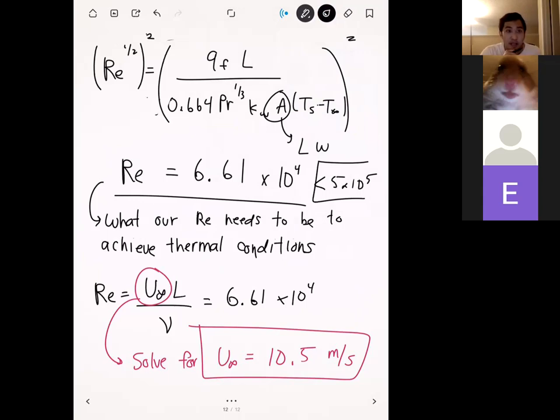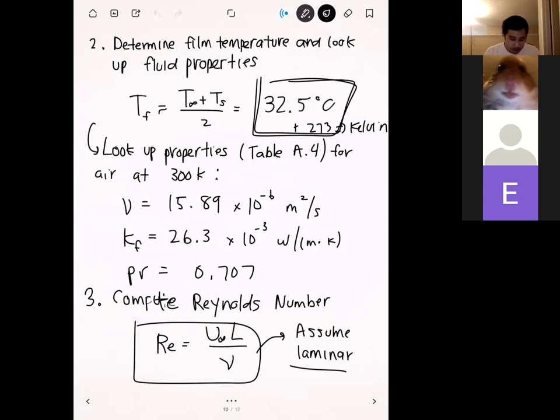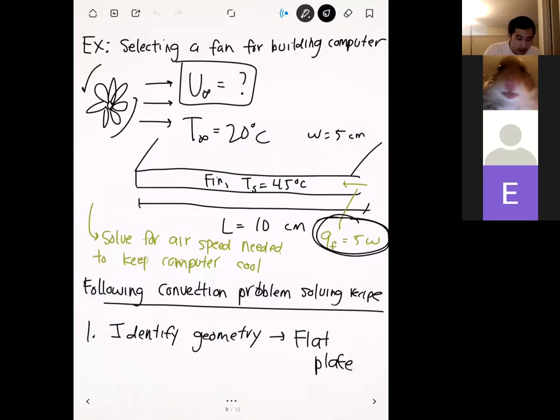Yeah. And so in that case, you would start with an assumption of mixed, because usually when the flow is all turbulent, that happens when you purposely trip turbulence. So if you have something like a barbed wire or some kind of trip wire here, that's basically going to force turbulence from the very beginning. In that case, you can just use a turbulent boundary layer. But in this case, we didn't say anything like that.